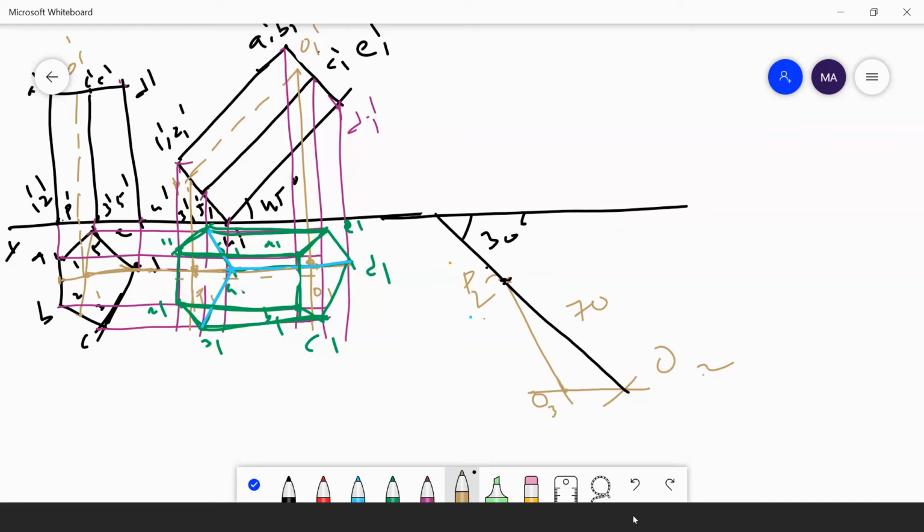After that, you take the compass. First, you measure the distance from P2. Listen carefully, very, very important. You are just projecting this green color pentagonal prism on this P2O3. You are simply projecting the given green color top view onto this P2O3. Understand? P1